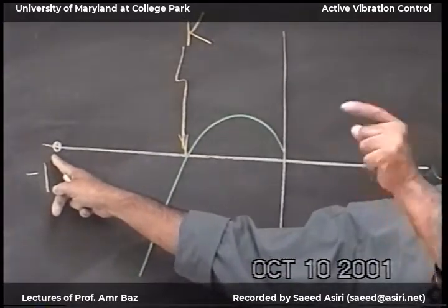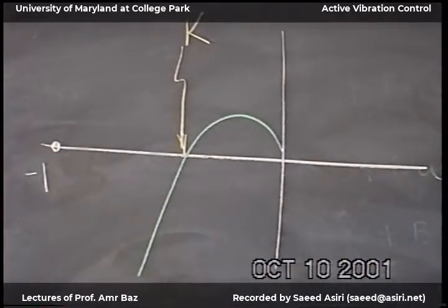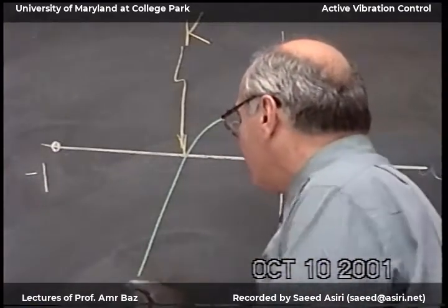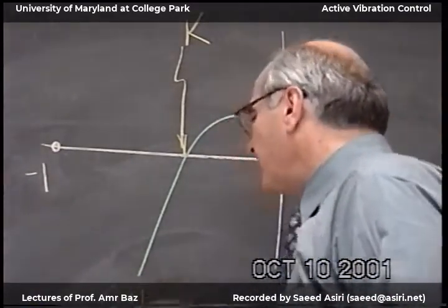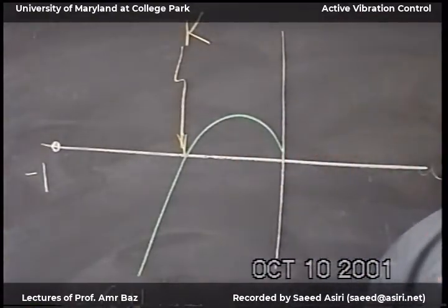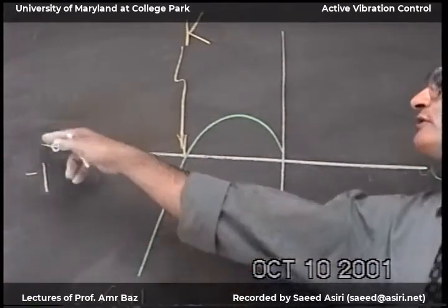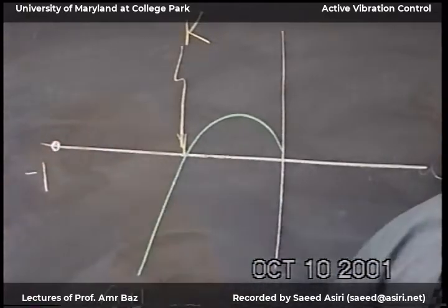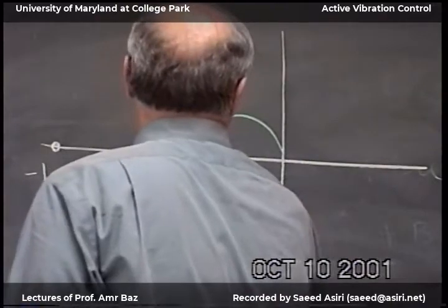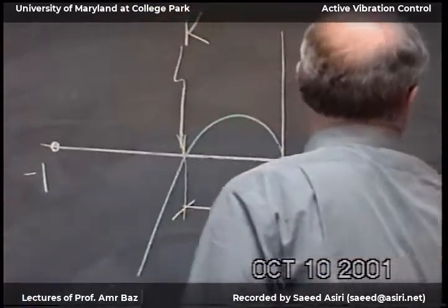This would be my gain margin. So now I'm plotting this plot for the G and H. This is the numerator, denominator multiplied times the gain of the system. And then this gain, how much can I increase it until this crossing point comes and hits the minus 1. So this will give me the gain margin. So this is a gain A, and the gain margin